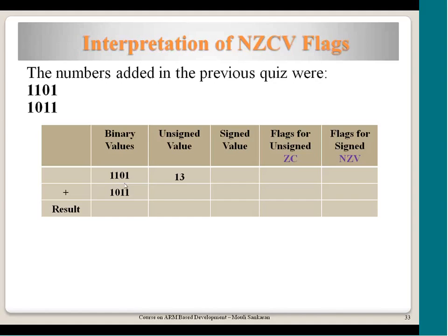So how do you convert this into a negative number? What does this correspond to? It corresponds to -3. How do we do that? You complement all these bits and add 1. What you get is 3. That is because this MSB is 1, you put a -3 here. Now similarly, you do this also, you will get 11 and -5.